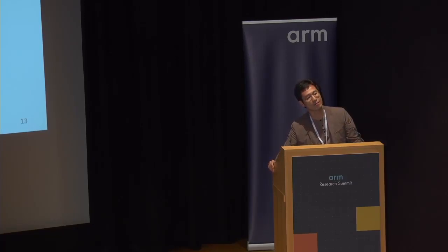Yeah, the system that you're modeling, does it have ECC for the memory system, or is it just a plain non-protected memory system? Thank you for your question. I'm sorry for not mentioning that. SRMT and ours assume that memory is protected with ECC. But still, while you are updating the memory, for example, when you calculate the effective address of a memory operation, they can still generate some errors.